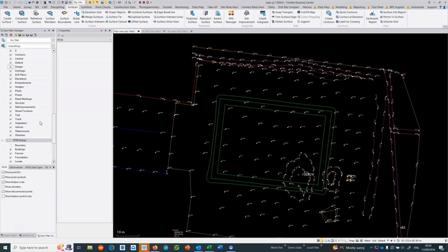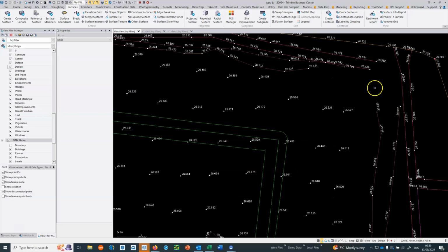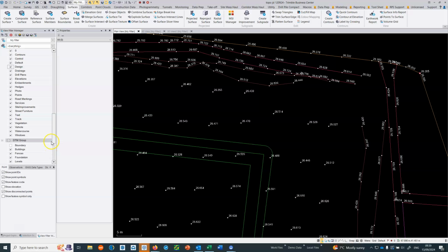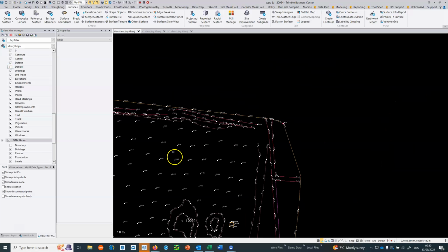So in this workflow, one requirement is all the lines need to be part of the surface, and there need to be bounding lines, not all the way around each individual area, but between changes of surfaces. And again, they need to be part of the surface, and we need to change all the line types to be surface texture edges. So fairly straightforward when we actually go through it. So let's just turn the design off.